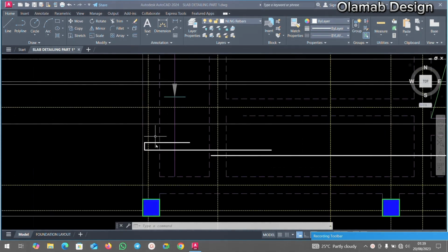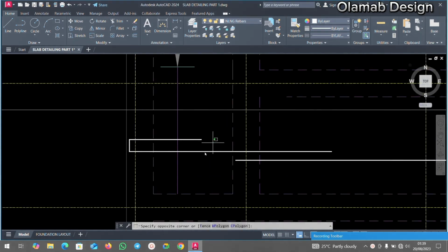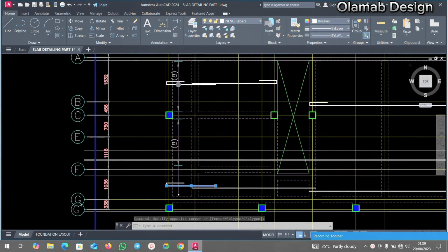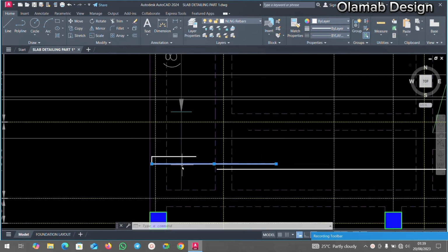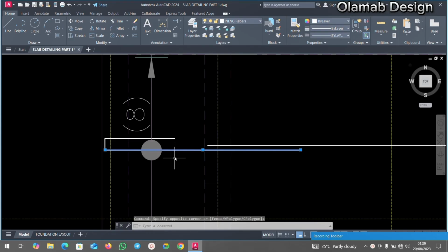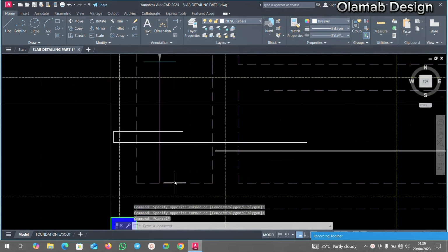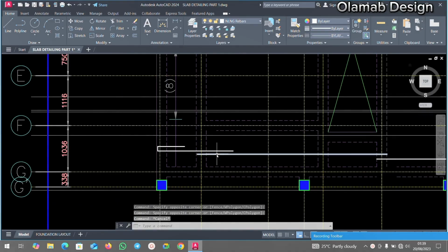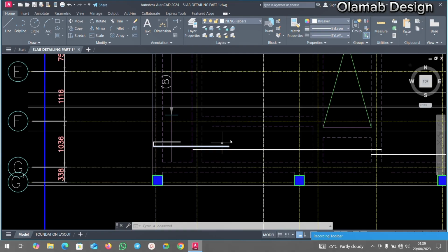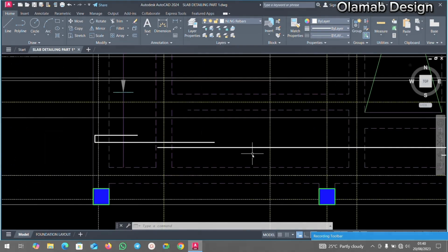Okay, what I mean is that this particular one I split here, you can choose to run this one down to this panel. This is because here this particular one is serving as the main bar and is also going to serve as the main bar. But the reason why I split it at my own hand is that once I know that the next panel is going to be bottom 2 and this one will be bottom 1, I always like to detail them separately.